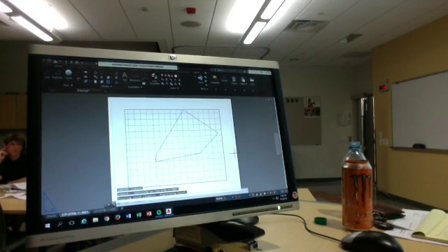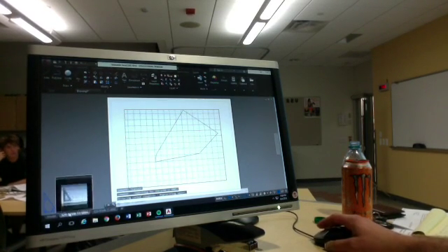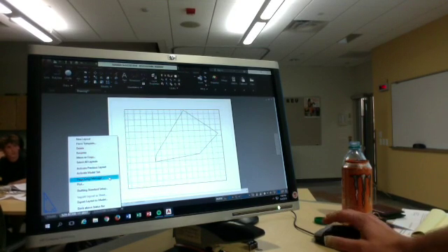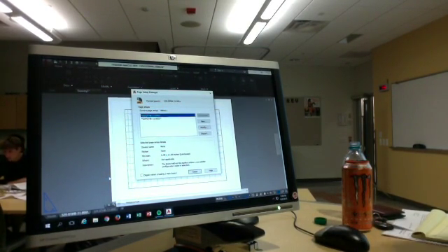What we're talking about here, though, is the actual Page Setup Manager. On your tab, you can right-click, and then you click on Page Setup Manager. When we actually change it, it's going to look very similar to when you go to plot something, but that's kind of the whole point: you're already set up to plot. You don't have to sit there for another 10 minutes and set it up.